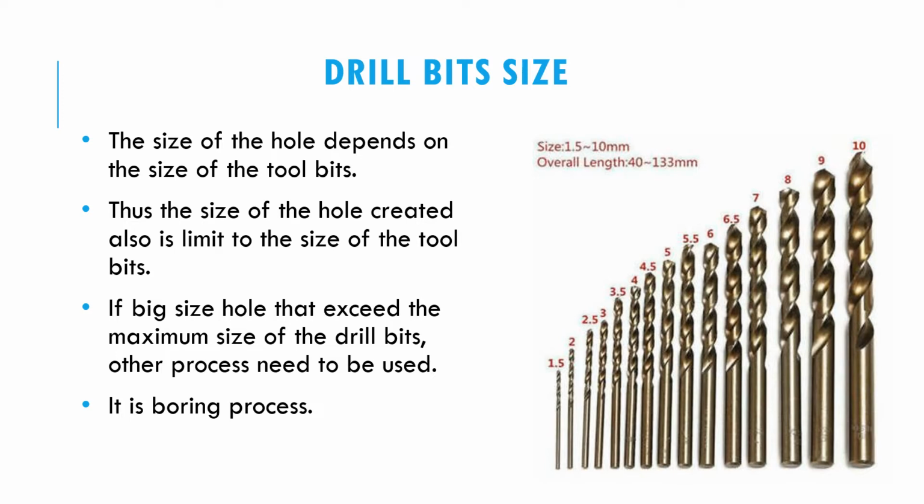There is a limit size of the drill bit. So if you want to create a very big hole, maybe first you can start with drilling the workpiece, and then you finish it with another process, which is the boring process.